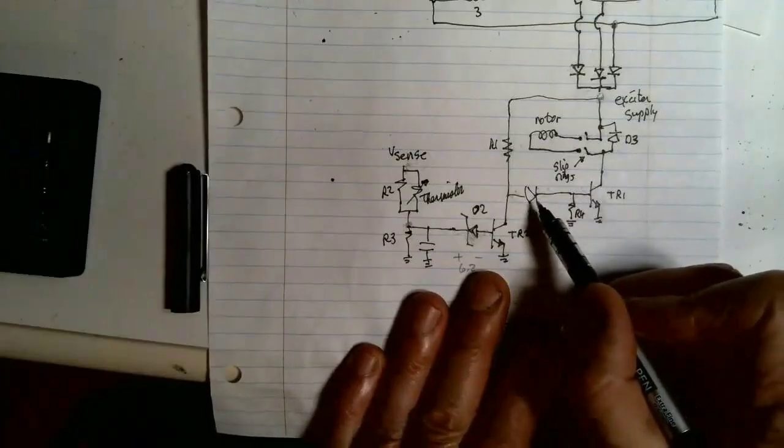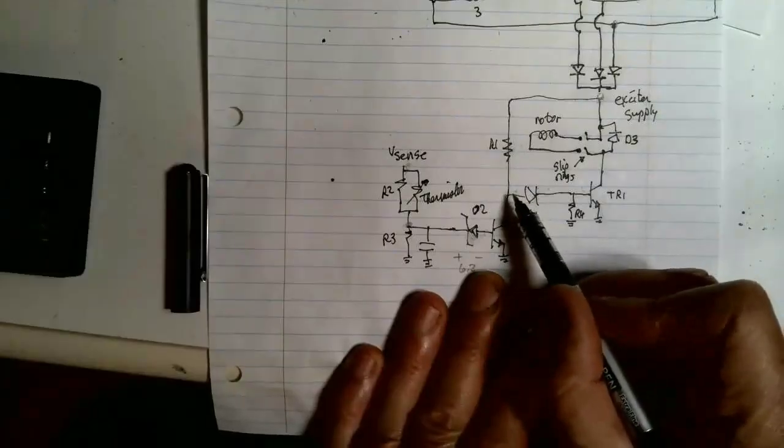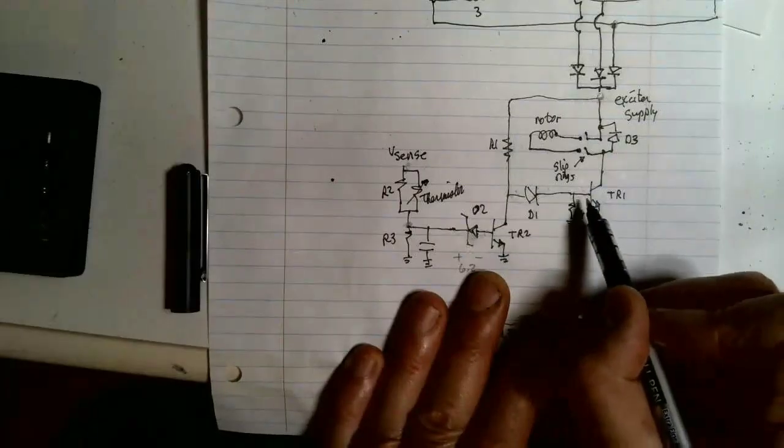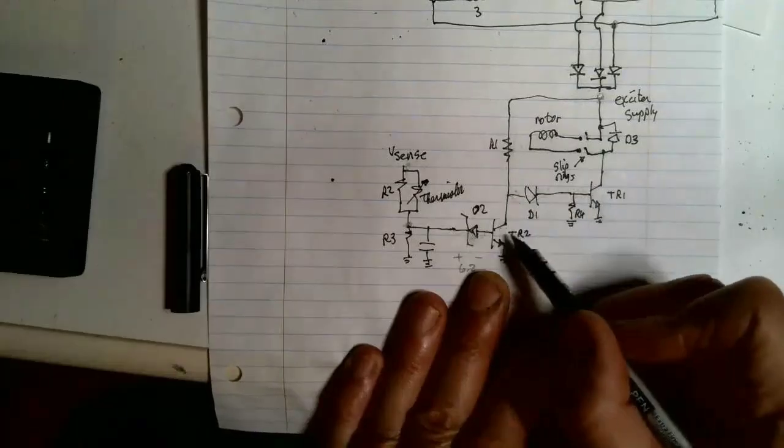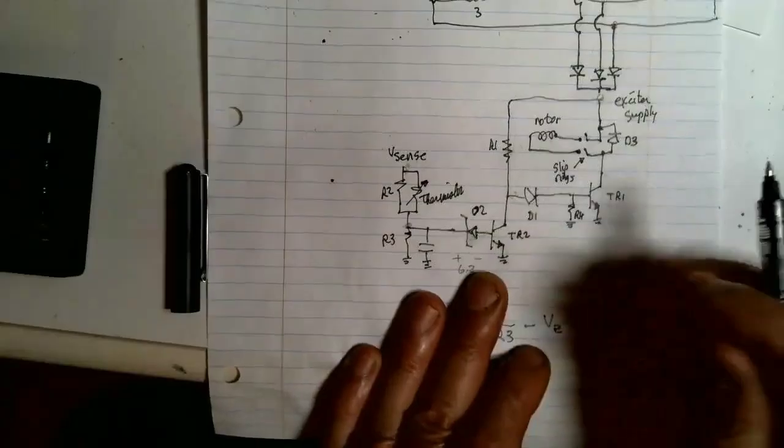All right, just for level shifting purposes. It's not used as a rectifier. It's not used for protection. It's just for level shifting. It just changes the voltage that needs to be here to turn on this transistor. It raises it up a little bit, makes this device work a little bit better.